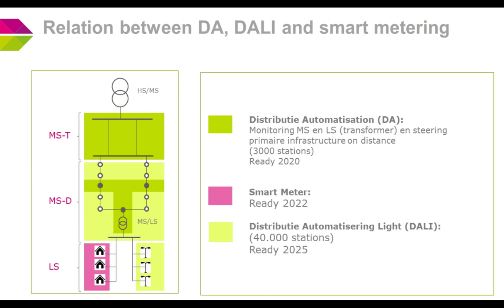We're operating this grid in a ring form, but we steer it as a star. So it is possible after a fault to switch the switches on and off. And in 2-3 minutes, it is possible to get customers energy again from the other line.